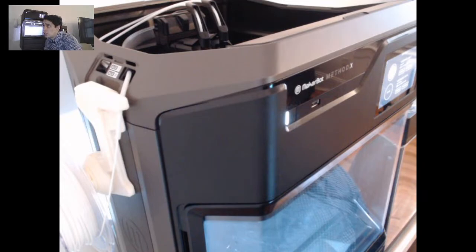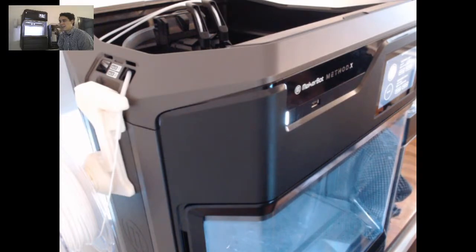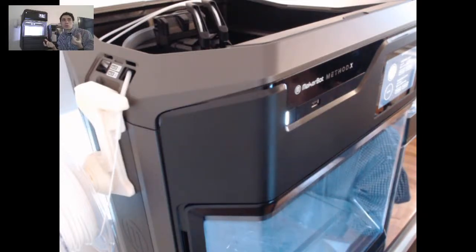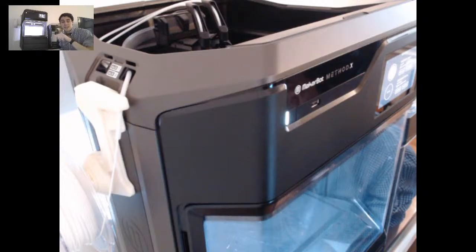Yes, it is. It's not recommended because many of the print profiles are associated to the filament. And that might not work well between different materials. What I mean is, if you start a slice with ABS and then want to switch over to a TPU or SEBS, you might compromise your print, because SEBS or any TPU will have a different print profile.